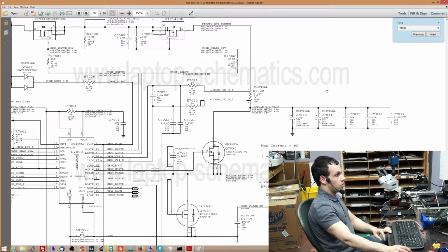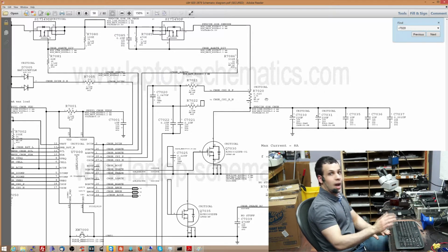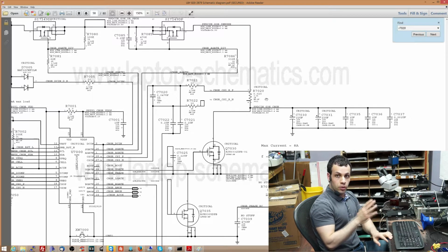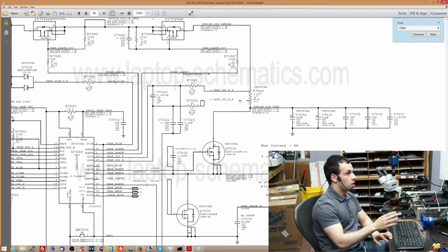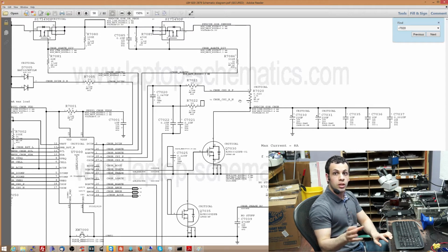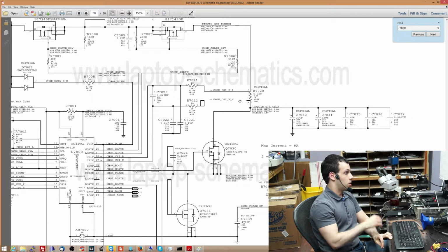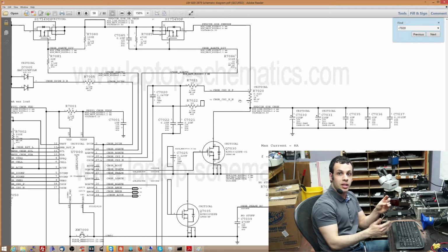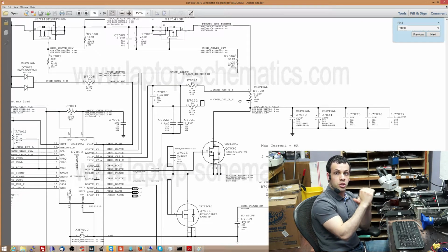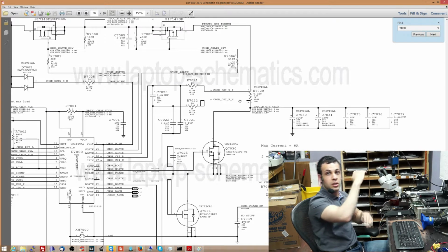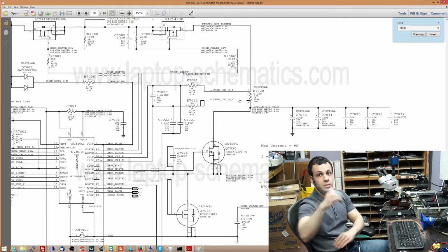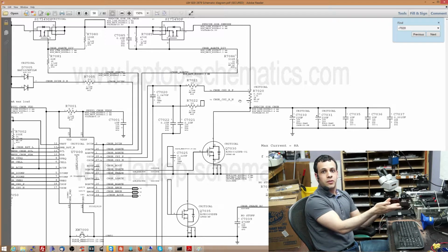So what we do is we put a resistor whose drop in voltage is known for any given amperage that's going through it, and then we measure the voltage difference. Since we know how much amperage the system is using when there's a certain voltage drop across the resistor, we tell U7000 or we tell the SMC, when you see this much voltage difference, we're using this much amperage. When you see this much voltage difference, we're using 5 amps. When you see this much, we're using 6 amps. When you see, let's say, 50 millivolt voltage difference across there, we're using 1 amp.